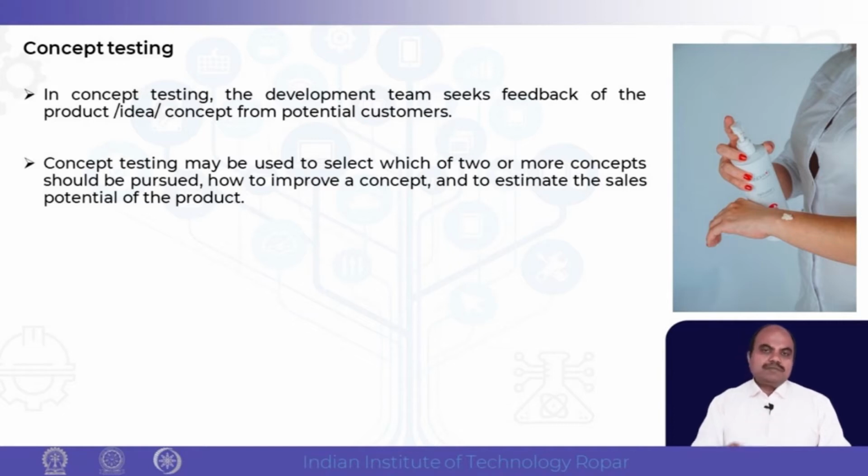Initially the problem which the consumers tell the designer is sometimes vague. So in the product specification document, we have seen how this vague statement can be converted into very specific technical requirements. Once we have these requirements in place, we can use various techniques, especially brainstorming, synectics, trees, and the gallery method, to generate a lot of ideas. Once the ideas are generated, in the concept selection and concept evaluation phase, we have evaluated the ideas using various methods.